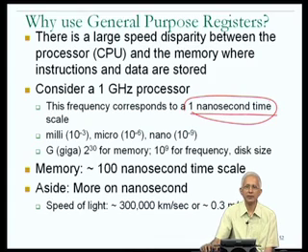If the flow of information in a computer chip is even 60% of the speed of light, then in the time scale of one of these fast processors, it's not going to be possible for a lot of signal flow to happen inside a large chip. So this is the significance of the nanosecond. Processors are quite fast, memories are slower, but processors are so fast that designing high-speed 1 gigahertz, 3 gigahertz processors is itself an art, because one has to very carefully lay out the components inside the processor so that the speed of transmission of the signal does not become an issue.